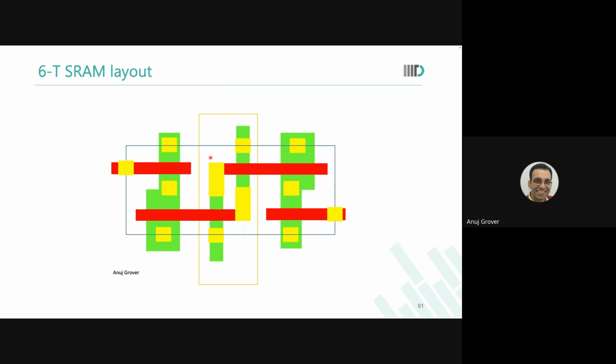No. So if I don't have to follow the DRC, I can bring them closer. Now what happens? The spacing between the two contacts becomes something like 0.1 micron, something very, very small, because I want to bring them as close as possible. And the spacing between two squares is now much lesser than the resolution of my lithography machine. It can't handle it. So I say, "Let's make a long contact."